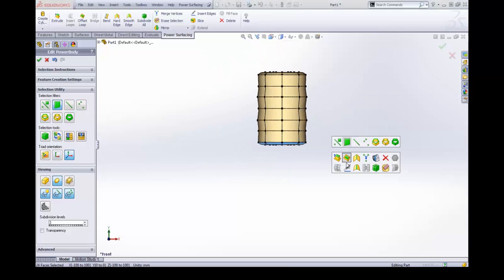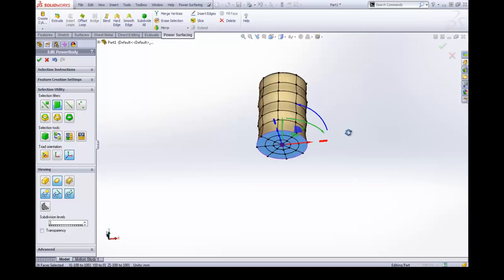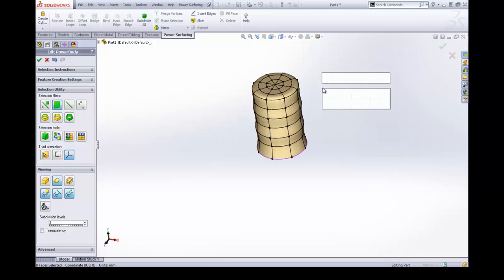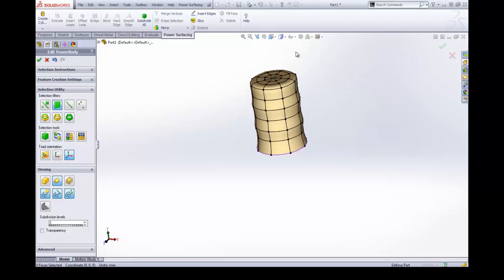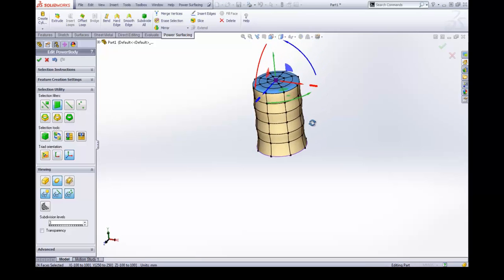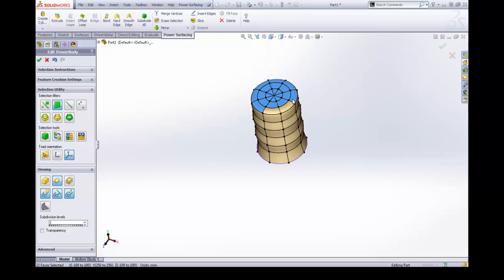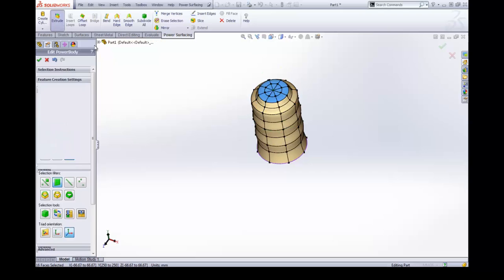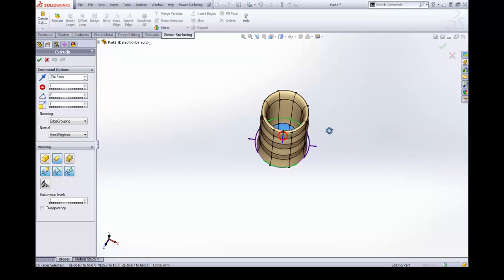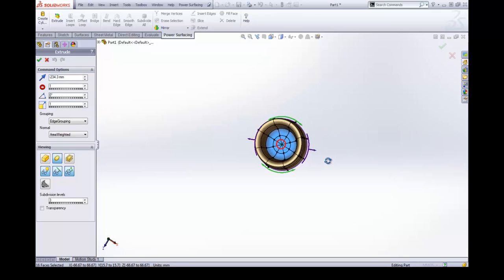And you'll see me right here going to hard edge that bottom, which is actually really cool. What it does is it gives it a corner piece, or a real sharp corner, if you don't want it to be completely tangent. And right here what I'm going to do is an extrude, but I'm actually going to do almost like a cut extrude. I'm going to take away everything in the middle so it actually is a mug. And you'll see me do a lot of right clicks.